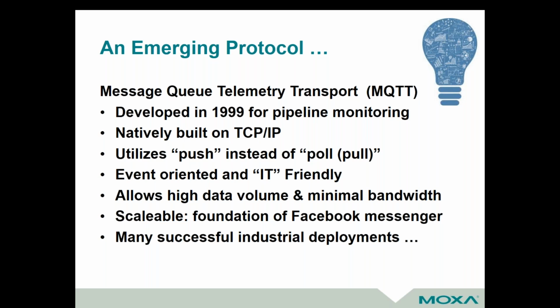It's a protocol called MQTT, and it's kind of interesting because its acceptance has been more in terms of IT, but its roots really go back to industrial automation for pipeline monitoring, dating back to about 1999. And it's a protocol that's built upon TCP/IP and utilizes this concept of push-type notification instead of pull. I'll share just a little bit of insight with you if you're not familiar with it, that it utilizes publish subscribe. So you might hear the word pub sub used for that. The really interesting thing is we're seeing a lot of interest in this, where it's kind of bringing both the operations and the IT teams together.